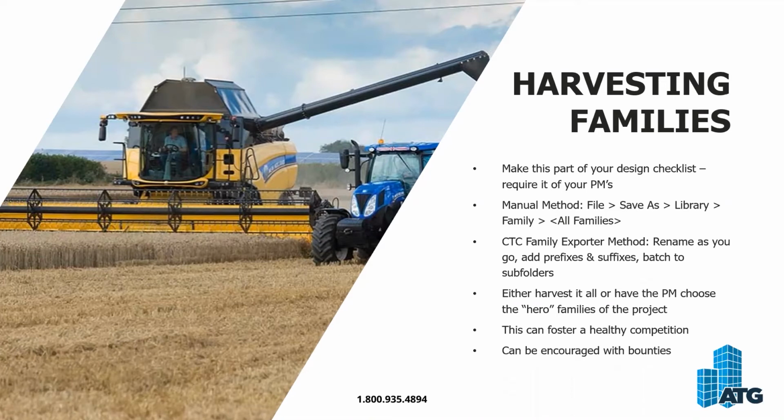You can utilize some freeware software that's able to deduplicate. And so if you have a lot of duplication of families that already exist in your content library, you can identify those with deduplication software, delete those files out, checking with a PM to make sure they didn't come up with a better version of it before you delete it. And then that leaves you with the unique files that you've stripped out that can be improved and then made available to your team. So it's a manual method, but I would recommend that you try to harvest everything out and basically require that as part of the PM's deliverable.